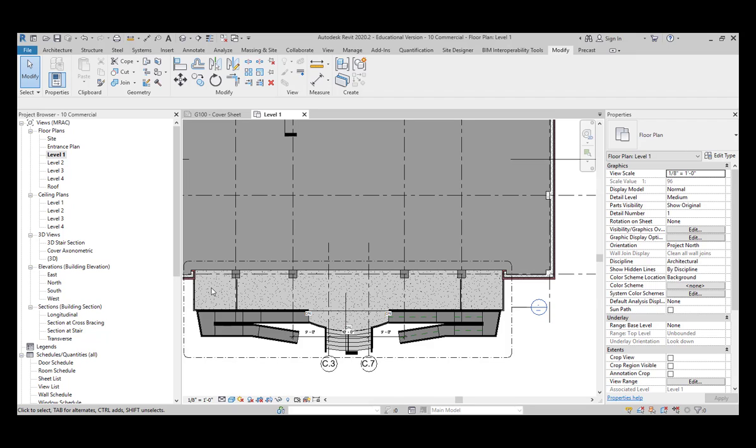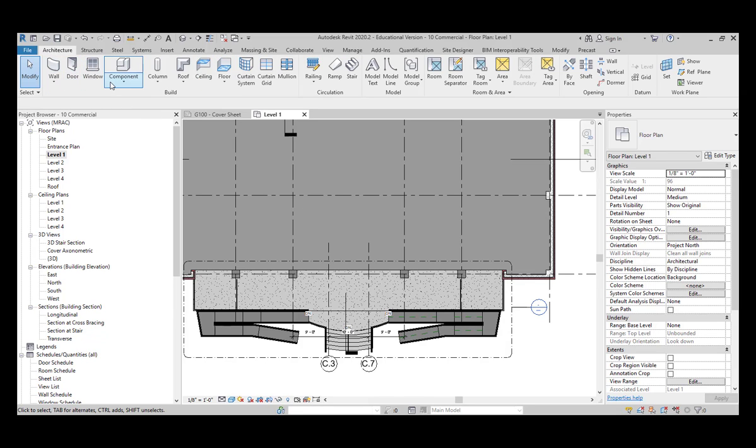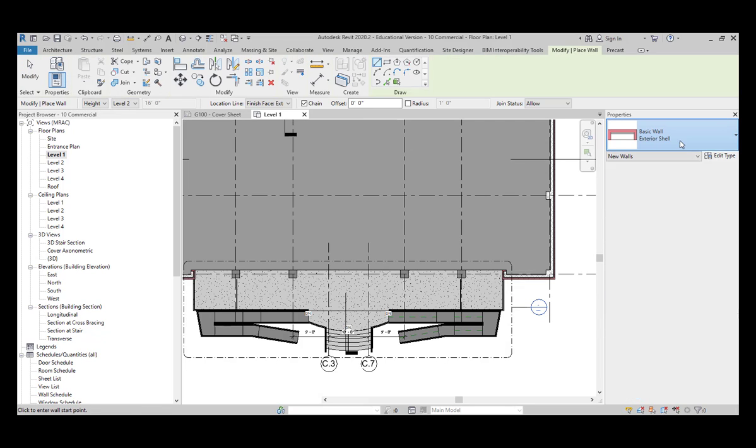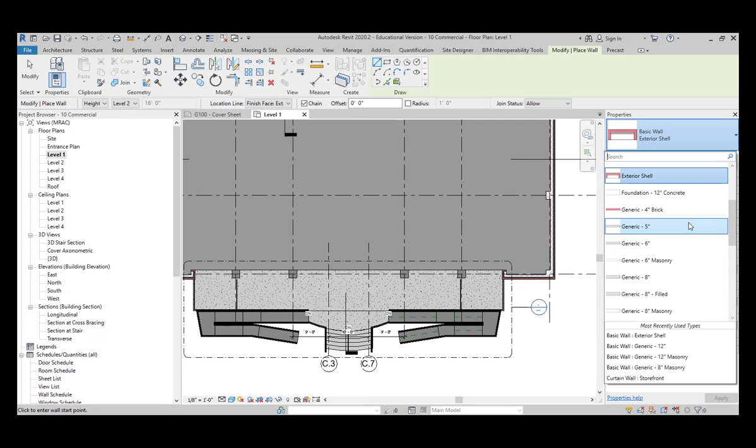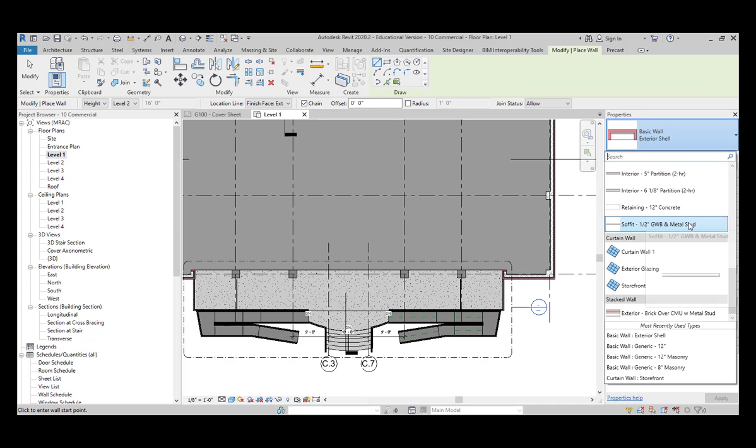All right, picking up on page 431, I'm going to create a couple of new walls. I'm going to go to the Architecture tab. I'm going to say wall. And what I want to do here is draw a curtain wall. So scroll all the way down to the bottom of this list. Now you need to read this stuff about working with curtain walls and wall system families on page 430. It's going to explain what's happening, but I'm going to show you the clicks.